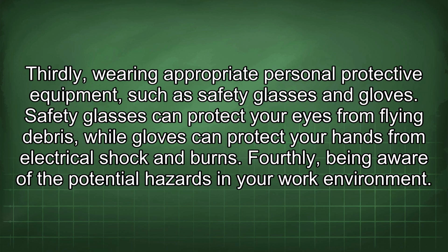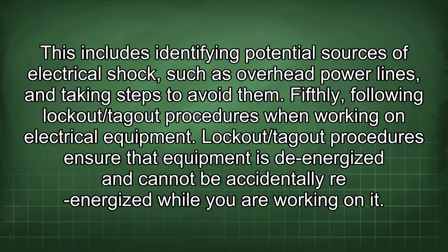Fourthly, being aware of the potential hazards in your work environment. This includes identifying potential sources of electrical shock, such as overhead power lines, and taking steps to avoid them. Fifthly, following lockout/tagout procedures when working on electrical equipment. Lockout/tagout procedures ensure that equipment is de-energized and cannot be accidentally re-energized while you are working on it.